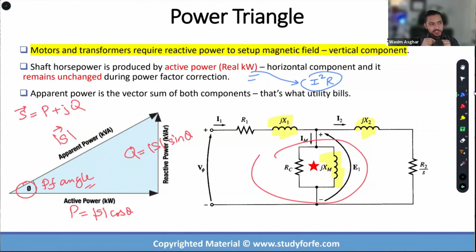And in the case of a motor as well as a transformer, the power is transferred from one circuit, let's say in the case of a transformer, from primary to secondary, not through an electrical connection, unless you have an auto transformer, but through electromagnetic coupling between the primary and the secondary windings. Okay. And if you don't have this inductor, you won't have that electromagnetic induction. So it's a necessary evil, like friction.